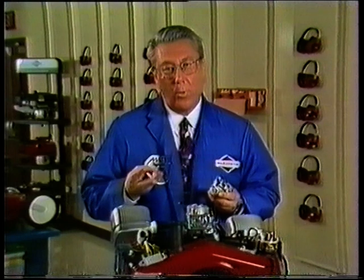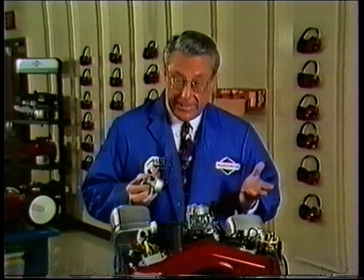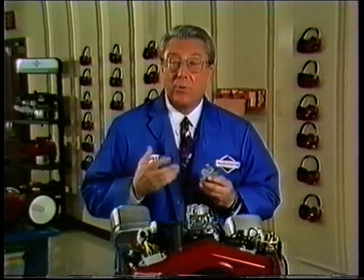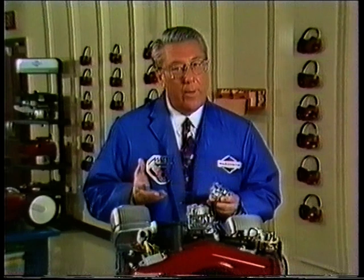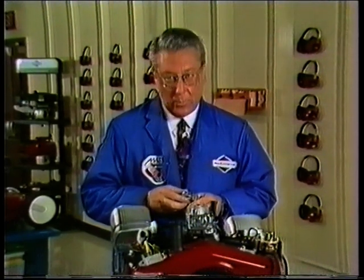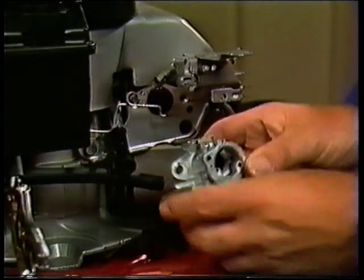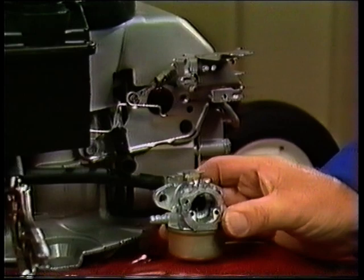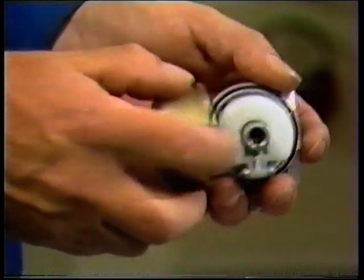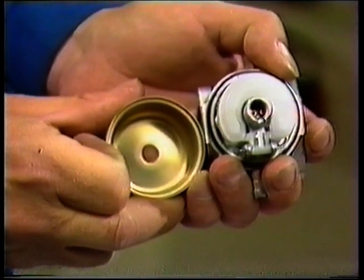There are typically 3 situations in which leakage may occur: while the engine is not running, sometimes called a static leak, while the engine is running, and during or after coast down. Let's consider these individually. To tell where a static leak is occurring, begin by removing the carburetor from the engine and removing the float bowl. Make sure the float assembly contains no liquid, since retained liquid can affect the outcome of your tests.